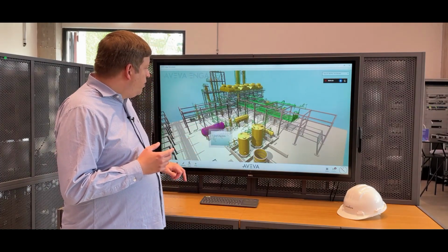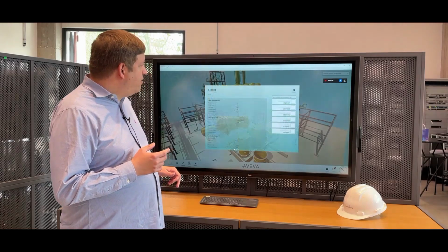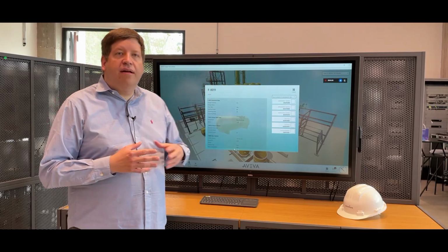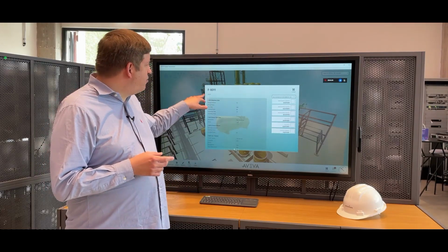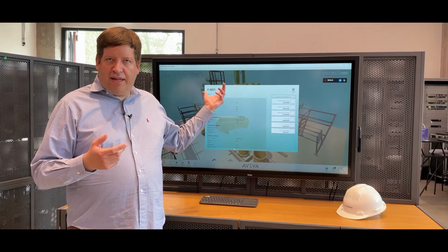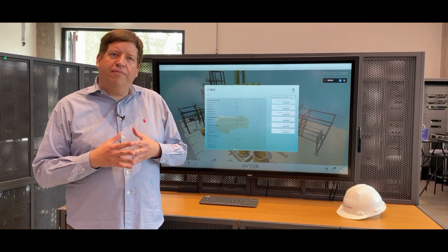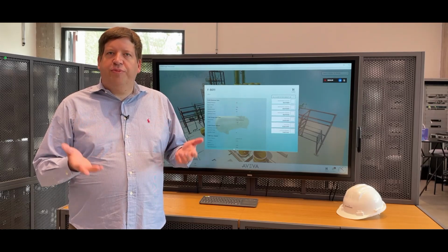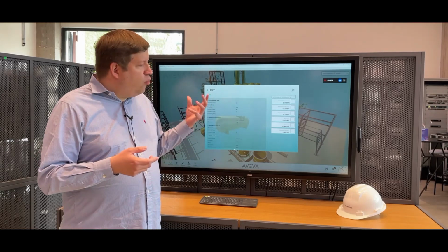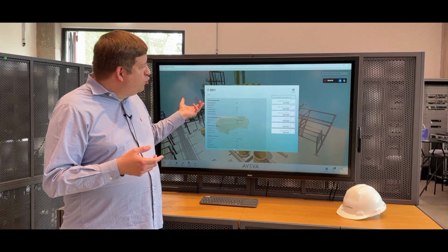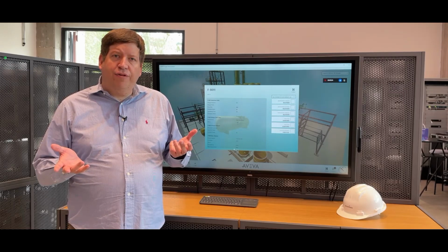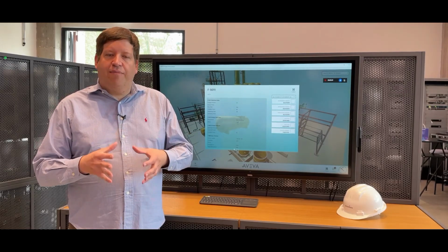And this comes to the second part, which sounds very easy. Every device, every equipment, every asset has the same name in all systems. Like in this case, this drum F8011 is called this way here in the display, but it should ideally also be used everywhere else. In your asset management system, your maintenance management system, for example, in SAP plant maintenance, or in your engineering tool like here in Aveva, or in your OSIsoft PI system as an example for a data historian, it always should have the same name, so you keep it synchronized.